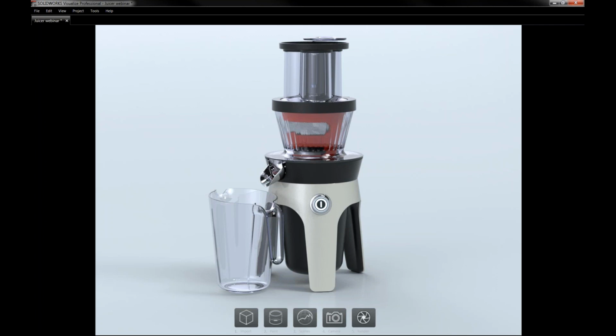However, if you really want to kick it up to the next level, we really suggest and recommend NVIDIA graphics cards, because Iray, the render engine inside of Visualize, is an NVIDIA product. Visualize will only use NVIDIA graphics cards to accelerate your rendering. So that's when you can take advantage of the Quadro line of cards or the other NVIDIA cards that they offer, which will really, insanely boost your render speeds. We're talking like Spaceballs ludicrous speed when it comes to pairing a graphics card with Visualize.